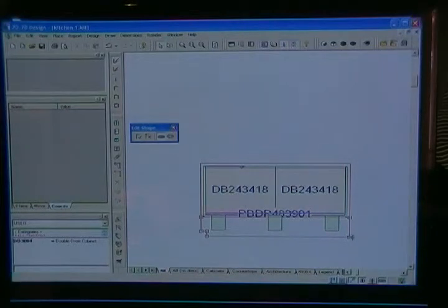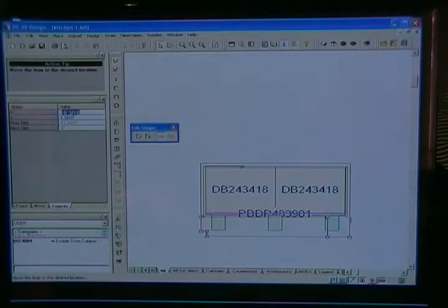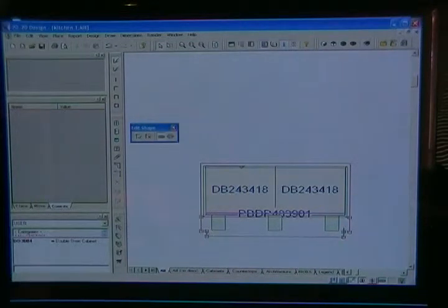We're going to do the same thing on the other end, but notice this time I'm going to be using a negative at a certain location. Why is that? Because we are going towards the left on one of my options. So in here I'm going to type -2, then click on tab and then type 2 because I'm going upwards, and press enter. And now I've got a notch on my countertop.